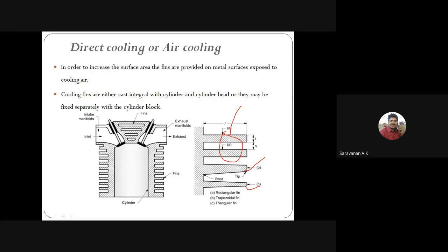The heat transfer rate can be increased by increasing the surface area. That is why, by increasing the number of fins, we can increase the heat transferring capacity also. However, the increased number of fins will reduce the spacing between them, which results in decreased heat transfer also.